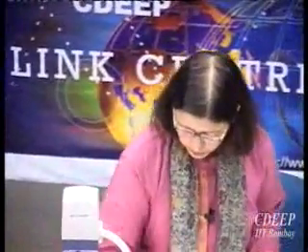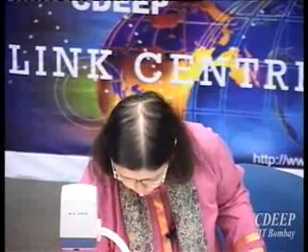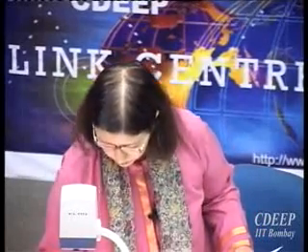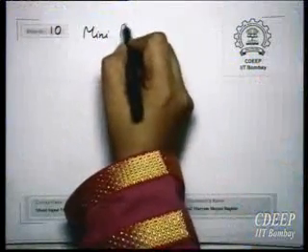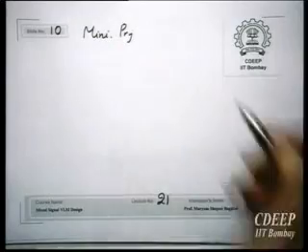Okay, so then you make a similar thing. Now you use current starved inverter as a component for ring oscillator. Therefore, you can make a simple digital VCO. Now the specifications will be this. I think 5, right? So one of you can focus on pulse frequency detector, one can be.